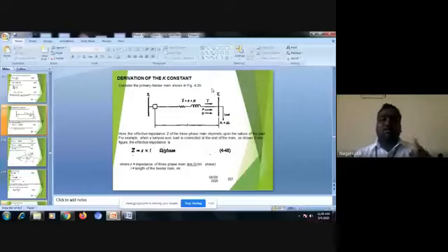With respect to Vs and Vr, you have some amount of current I through that primary feeder. With the current I, the resistance R and reactance X give P amount of active power and Q amount of reactive power.